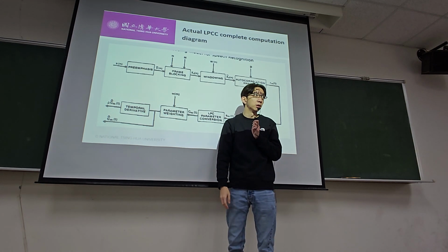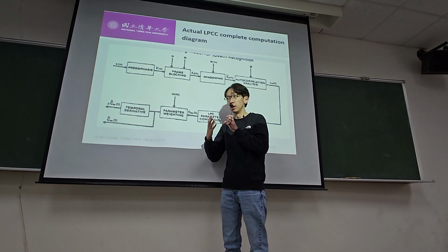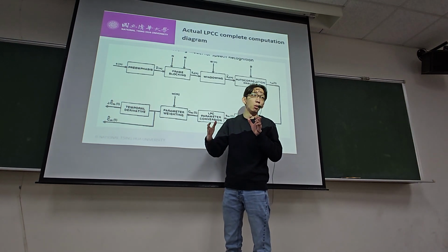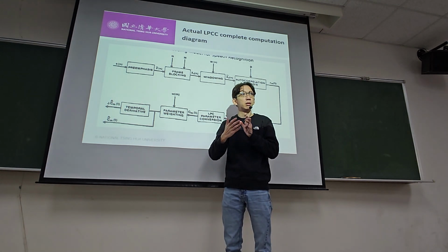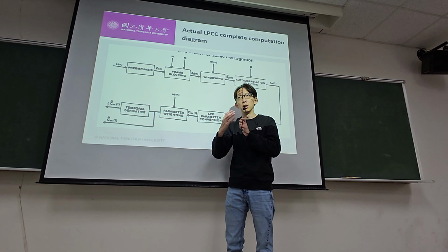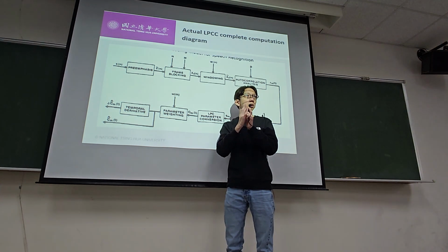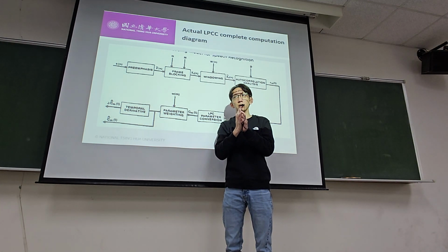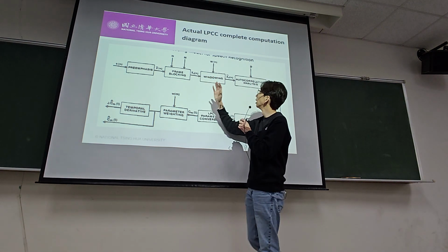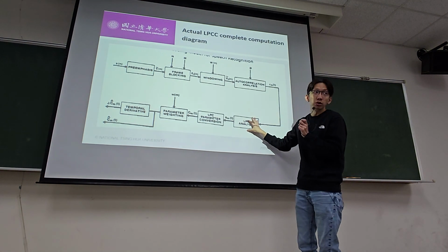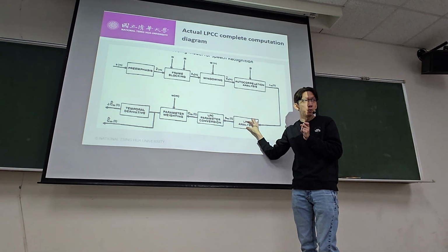The length of the signal gives us the sense of whether we're doing a narrow band or wide band analysis. The windowing that we apply will change the side lobe leakage and also the main lobe width, that is, how precisely you want to get the frequency. That choice you can make. This process is trying to do frequency analysis, spectral analysis.